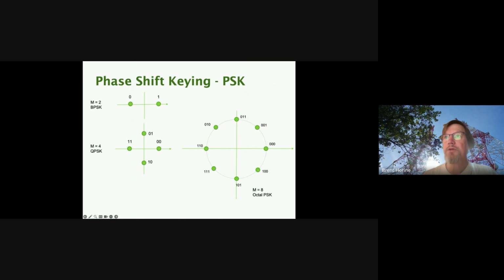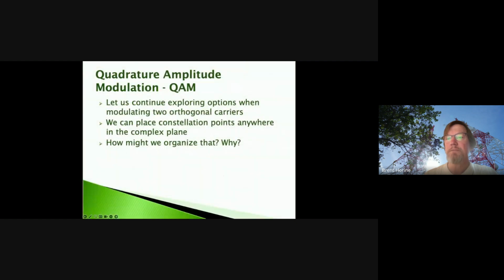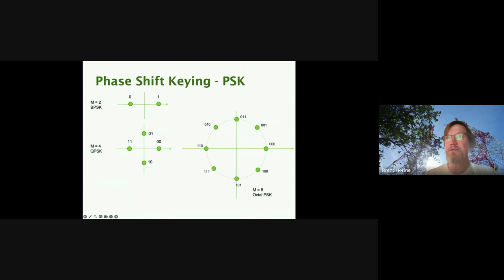So if you pick a constellation point and you look at its nearest ones, that would be this one and this one. This one's a little farther away, right? So that distance is farther than these distances. And so when you look at the nearest neighbors of any given symbol, you see that the bits only change by 1. So here 0 to 0, 1, only that bit is changing from here to here. Only this bit is changing from here to here. Only that bit is changing, and from here to here. Whoops. Only this bit is changing, right?